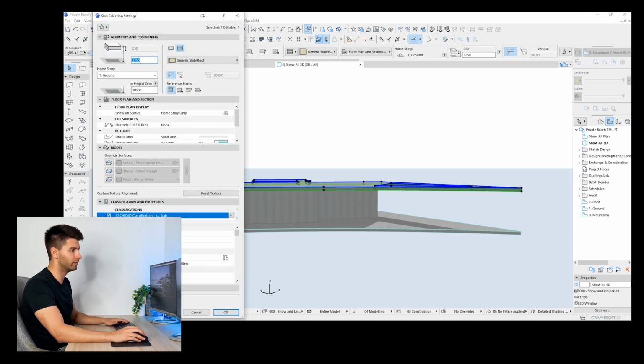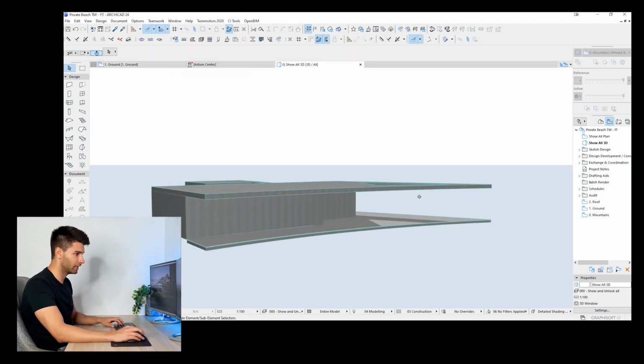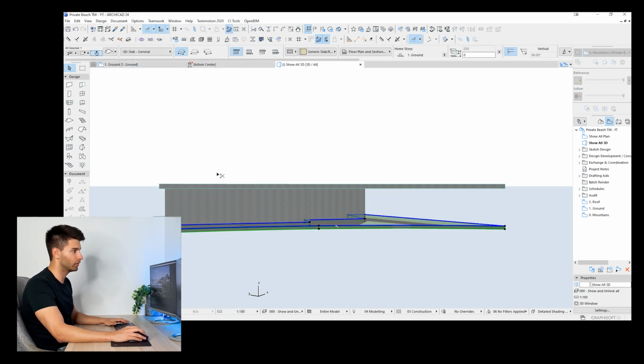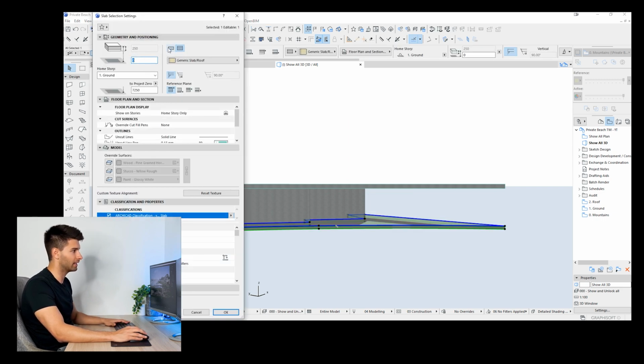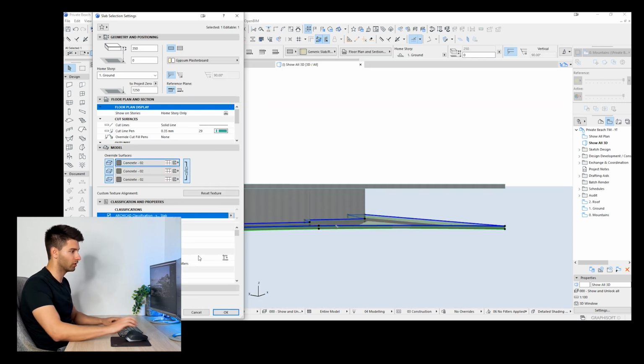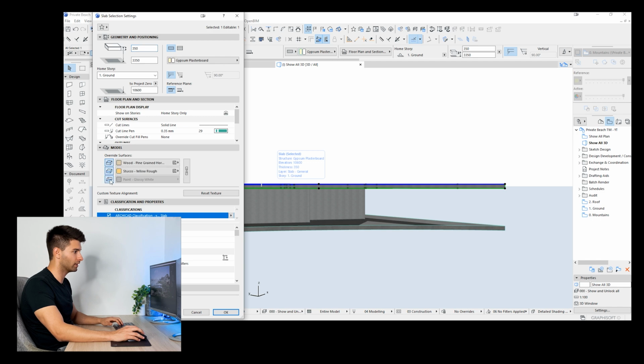That's 250. It'll probably be about 350, if not more. And now we're starting to see our structure come into shape. What we're also going to do with the bottom slab is recreate that to 350 mil to give it symmetry more so than anything else. And we're going to start changing some materials around. So this will be concrete. The actual roof itself will be concrete as well.